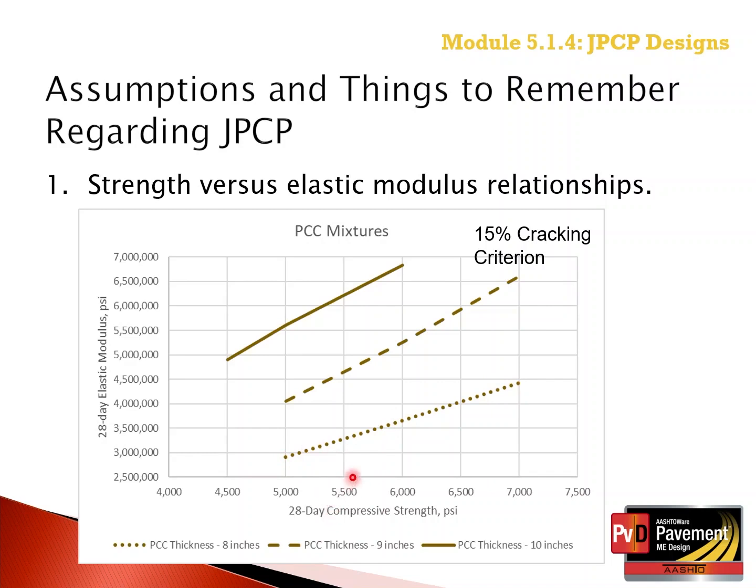And again, this shows the relationship between the 28-day compressive strength versus the 28-day elastic modulus. So at the end of the design period, the software will calculate 15% cracked slab. Simply, as the 28-day compressive strength increases, there's a potential increase in the 28-day elastic modulus, so that the design criterion of percent cracked slabs is 15% at the end of the design life.